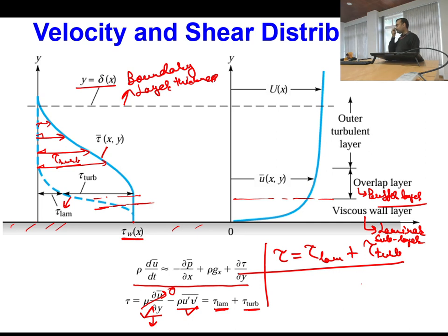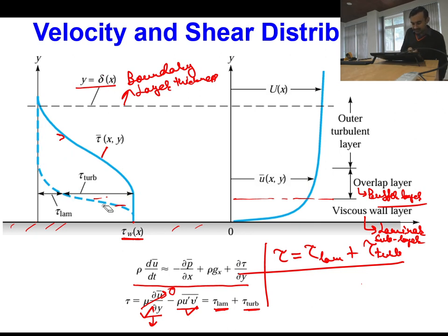In this case, the dotted graph is being shifted up, each for different values of y, which give different lines. This dotted graph you are trying to say? Yes. What I am trying to say is that this dotted graph is nothing but my laminar stress. This is my total stress. If this dotted line is approaching the reference line, it means up to this zone I don't have any laminar stress. So whatever stress is coming here is only because of the turbulent contribution. Have you understood now?